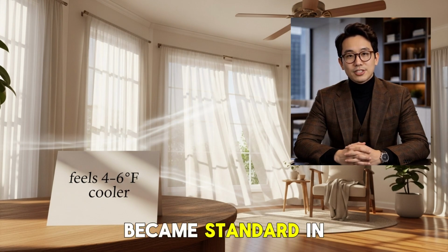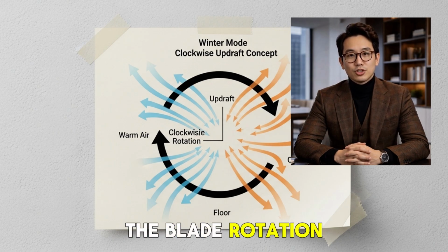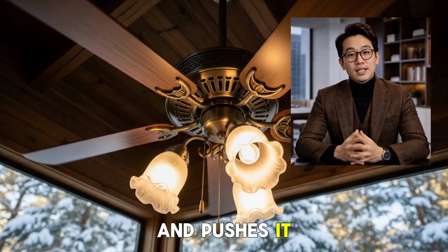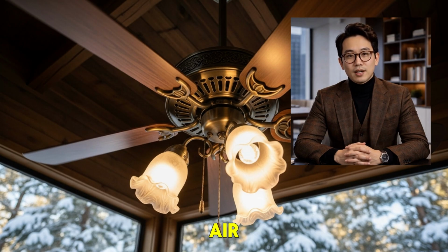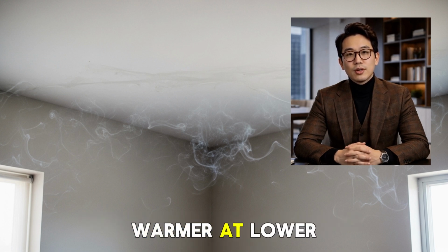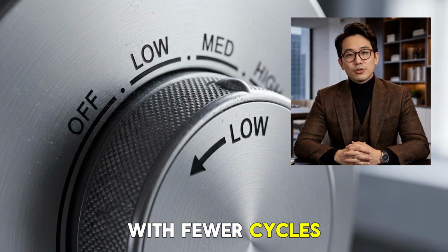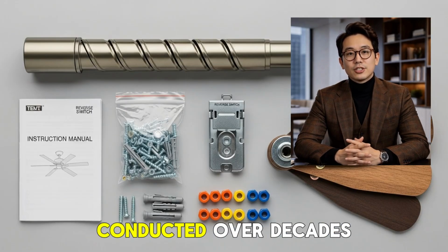Then central heating became standard in homes. Engineers realized ceiling fans could serve a second function during winter if the blade rotation reversed. Clockwise rotation, when viewed from below, pulls air upward along the fan axis and pushes it outward and downward along the ceiling and walls. This gentle circulation pattern redistributes the warm air trapped at ceiling height back down to living spaces without creating a direct breeze that would make occupants feel cold. The warm air recirculates, temperature stratification decreases, the room feels warmer at lower thermostat settings, and heating costs drop because the furnace maintains desired temperatures with fewer cycles. This is not theoretical. This is measurable thermodynamics documented in HVAC engineering studies conducted over decades.